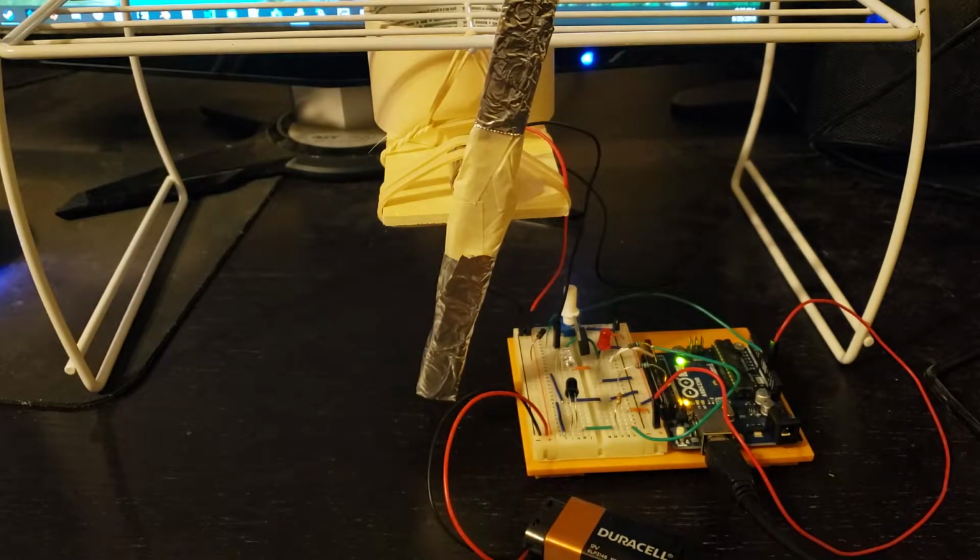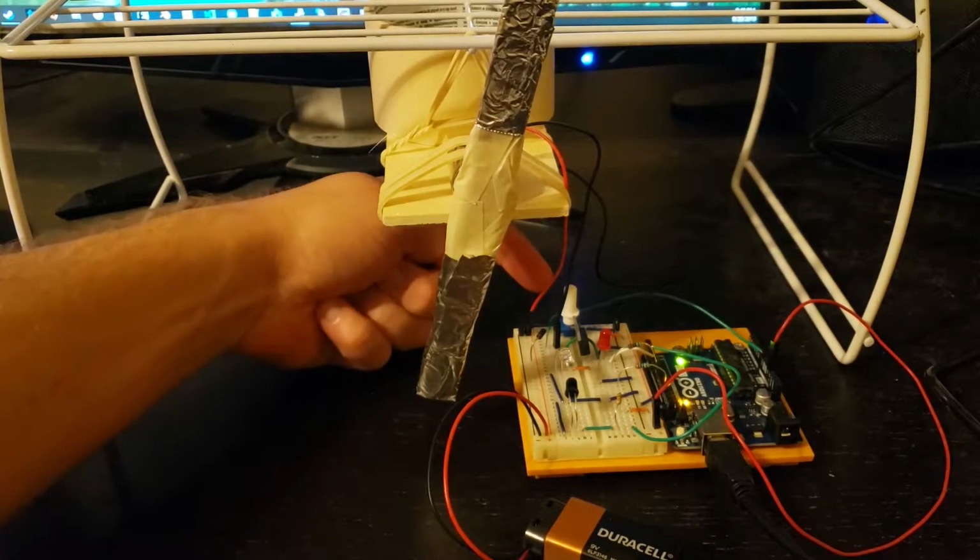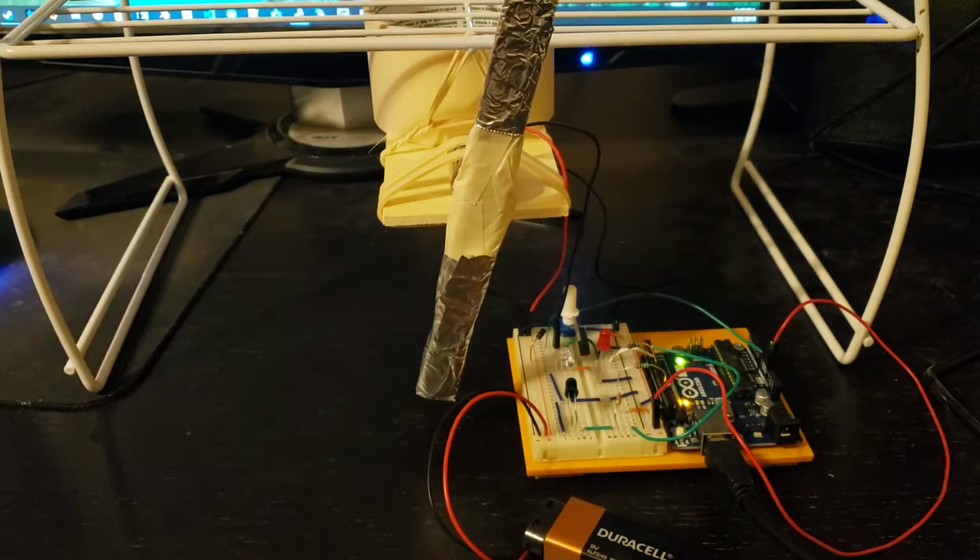After that, I was able to control the motor from software, but instead of programming just a simple spin up and spin down that repeats every time, I decided to add a potentiometer back here, which allowed me to control the PWM value and thus ramp it up over time, but be able to dictate it myself.